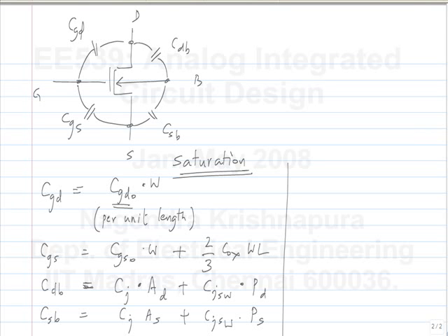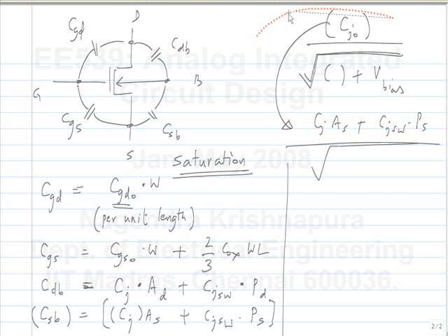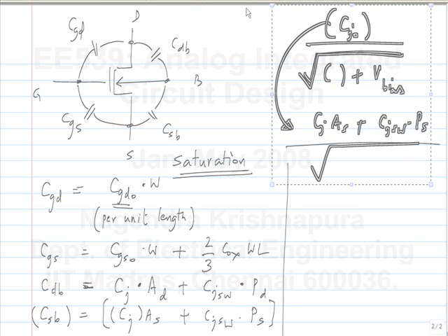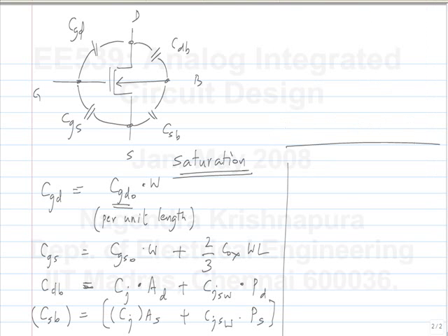Yeah, actually it is a voltage dependent capacitance. So this is just some parameter that shows how much the capacitance is, and it also depends on the voltage, right? The depletion capacitance of the junction is some basic capacitance divided by something plus the reverse bias voltage. Okay, so that is included in this, but for hand calculation certainly we will not be using any of this. But especially with the low voltage technologies we have today, the amount of variation is also small. Okay, we said this is in saturation region. How do these things change in the triode region?